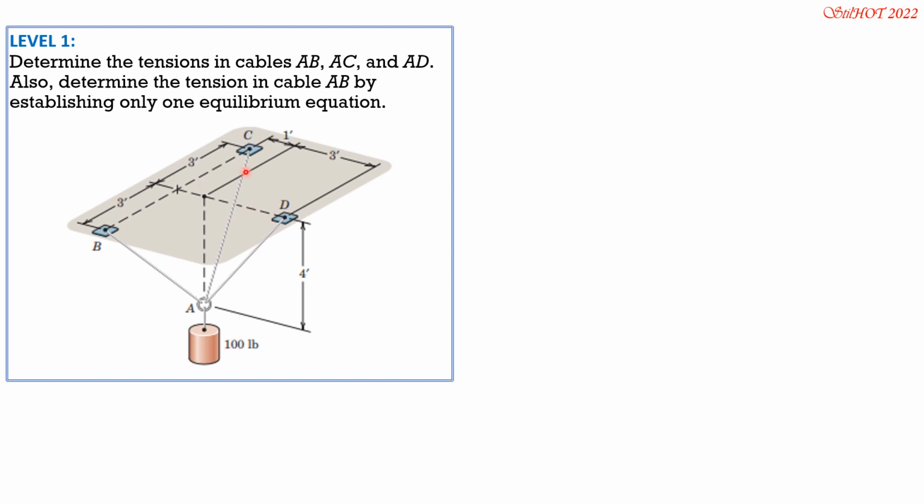But we can also solve this by expressing the tensions in vector form. If you do not express it in vector form, you can solve it by the scalar approach. But the best solution is expressing it in vector form because everything is there, the x, y, and z components. So tension, let's have this orientation. Tension AB is equal to 3i.